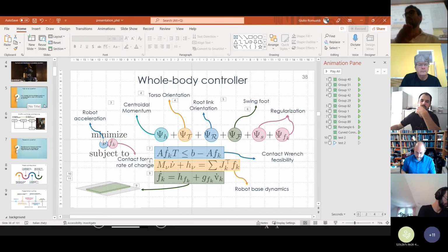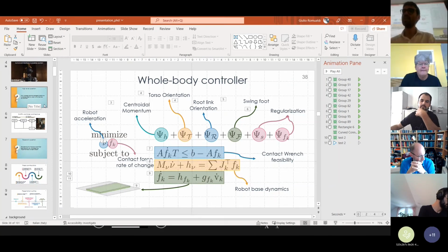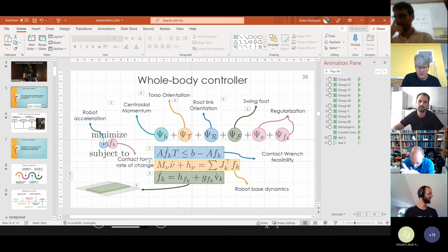Yeah, it's moving for control, but your planner, if everything. No, actually the planner doesn't consider the ZMP at all for the simplified model control strategy, and it is constant. As a future direction, we may think of having the heel-toe motion, so the movement from the heel to the toe for the ZMP. Okay, cool.